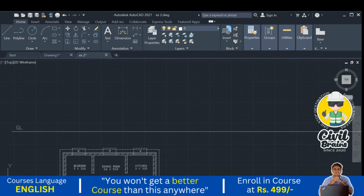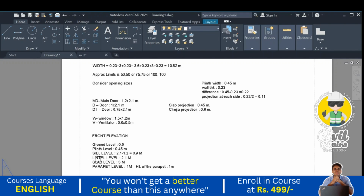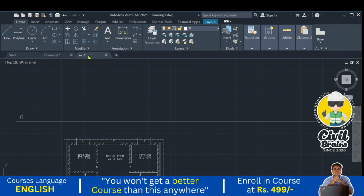the levels. So which is the first level? Ground level, 0. What is the next level? Next level is plinth level, that is 0.45. So I take the offset command, press enter, 0.45, press enter. I just mark the next level.